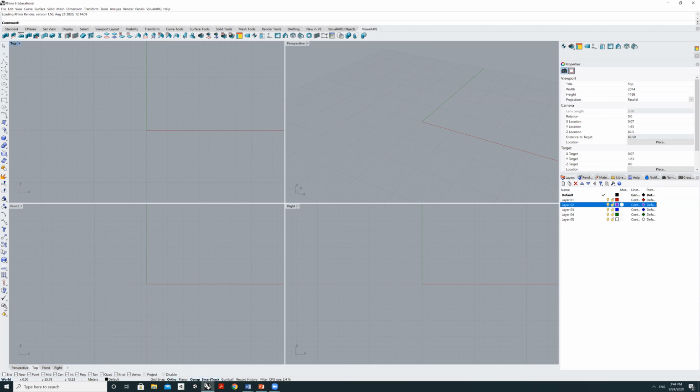It's very similar to any other modeling software, where the different objects can be assigned into layers. And you have the command line up here, which is the way you pass commands to the Rhino interface. I'll show you how to use this in a second. And you see some other more direct tools that you can apply from the toolbar on the left-hand side. We're going to use this sometimes. But as you can see, there are many options for interacting with the Rhino engine, but we will mainly do so through the command line.